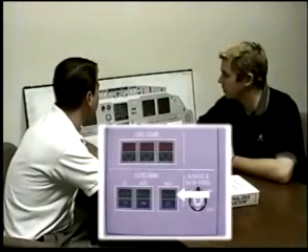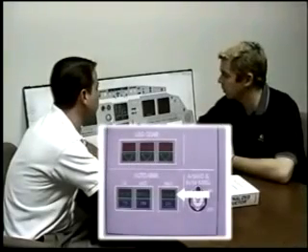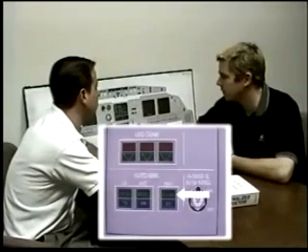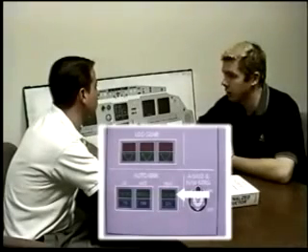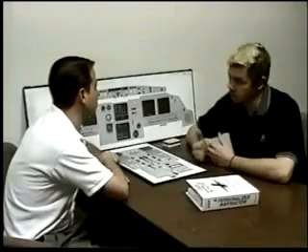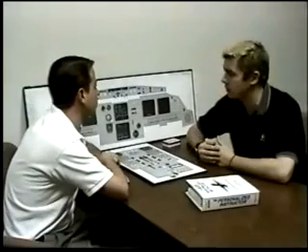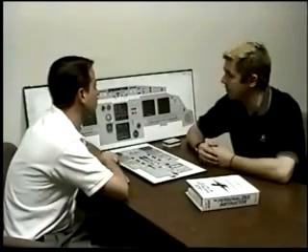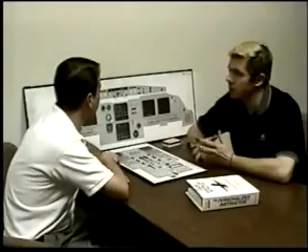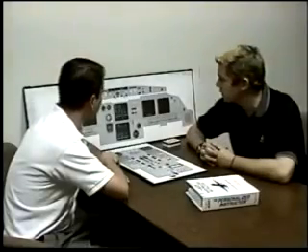Decel just means that we've achieved 80% of the deceleration rate that we're looking for. By the way, we don't have to achieve that deceleration rate with the brakes. We can do it with reverse thrust or any other source. As long as that deceleration rate is occurring, it's happy. If we're not meeting that deceleration rate, it will then start to engage the pucks.